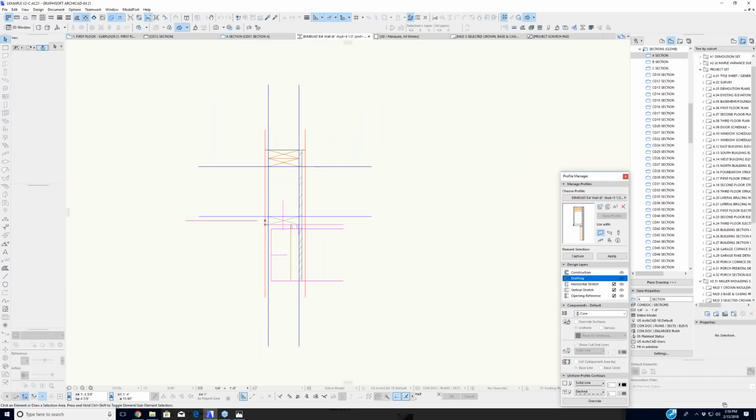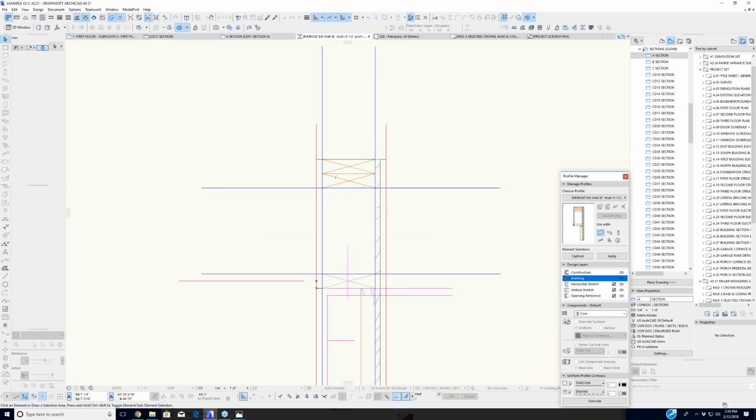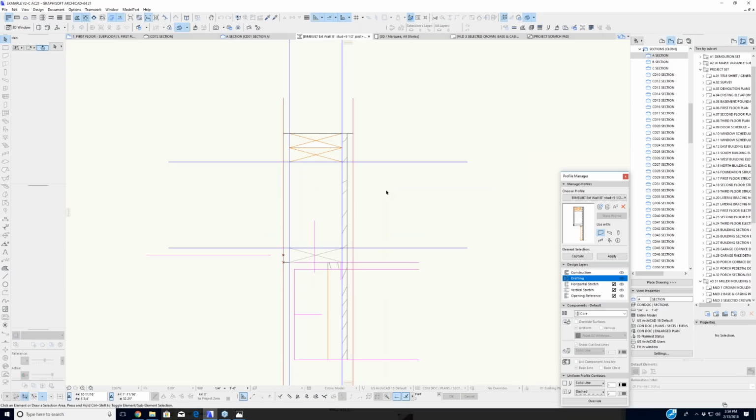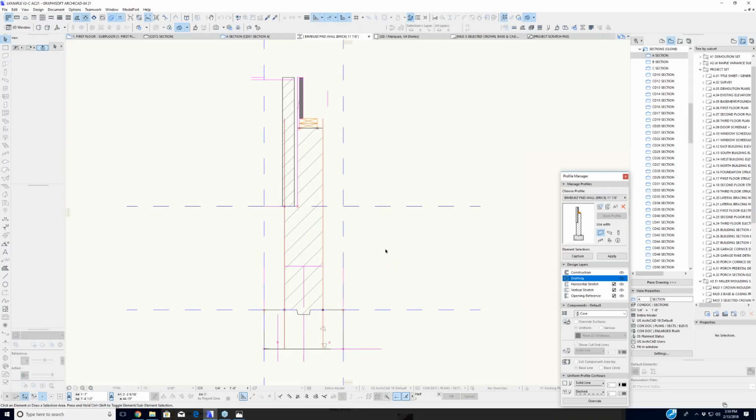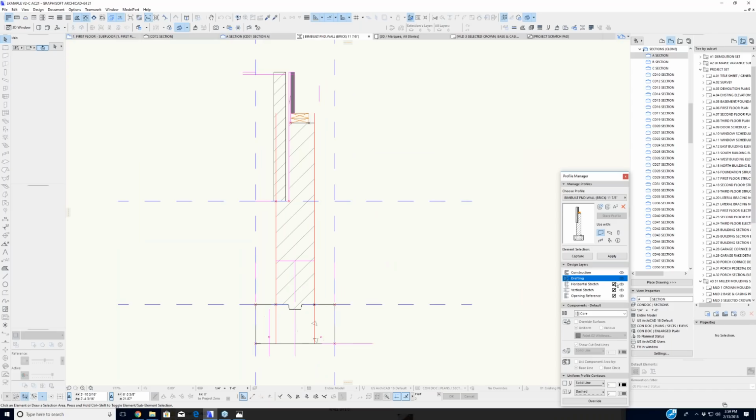Yeah, so that's just an important tip for all of you who are wondering how to do framing like that inside a complex profile. You can't draw lines. All you can have is the lines between adjacent fills, each fill representing most of the time a skin like plaster. But in the case of the framing, those X's are created by 4 separate fills that have lines between them because they're different types. They are just named slightly differently, and that's why they show up as if they were made differently. So we know that they're actually 2 pieces of wood stacked on top of each other with an X to indicate that they're cut. But for ArchiCAD, it thinks that there are, in that case, 8 little triangular pieces of something. It's a kludgy workaround, but it actually works quite well.